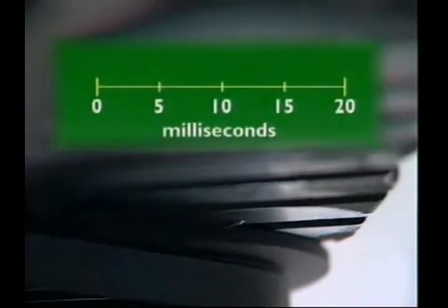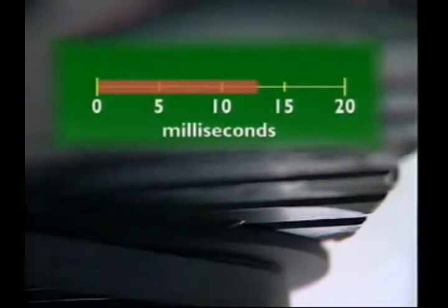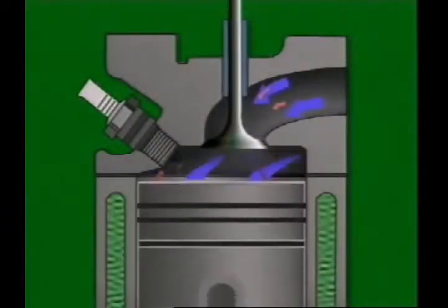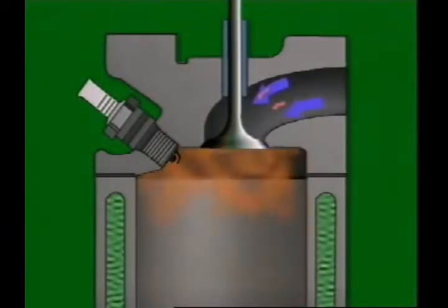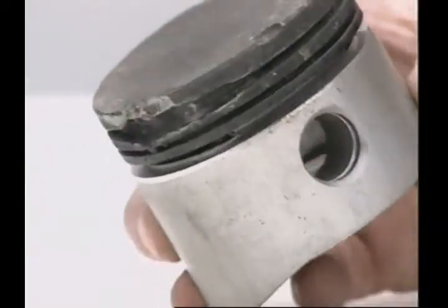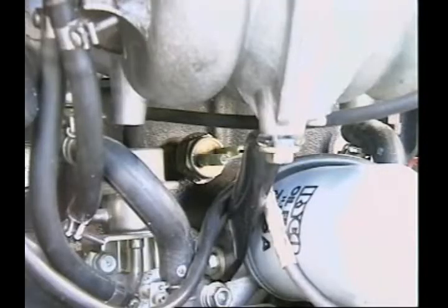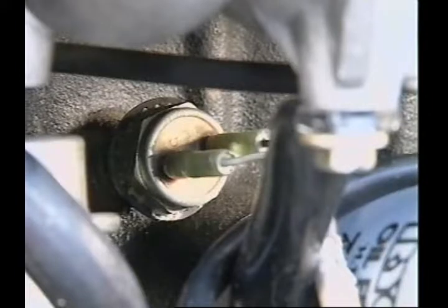Corrections to ignition timing, combined with those to the injector opening time, provide the optimum values to achieve the best combustion. With higher compression ratios, there is more risk of detonation and damage to the combustion chamber. A knock sensor allows ignition timing to be calibrated to achieve the best setting for normal operating conditions.